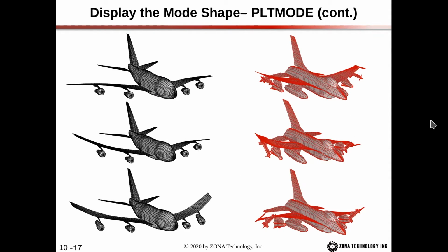And these are some examples of interpolated mode shapes on the aerodynamic model. We have a transport aircraft, and then a fighter aircraft over here. Just visually looking at these, we can see that the motion of the engine and pylon follows the wing, and it's connected to the wing. That indicates that we have a correct spline among all these components.